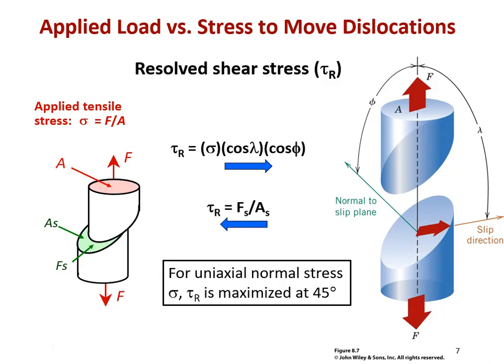And of course, beware that the angle with respect to applied stress for your maximum resolved shear stress will change depending on how many axes you've loaded. The 45 degree maximum will not count if you have biaxial or triaxial loading. This is only a uniaxial tension-compression relationship.